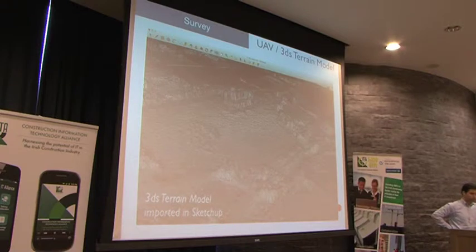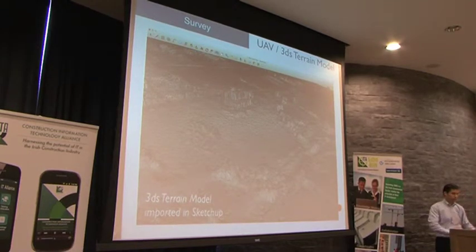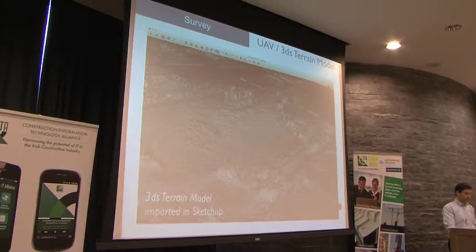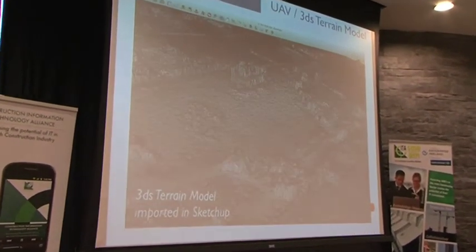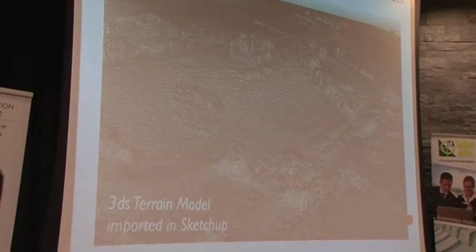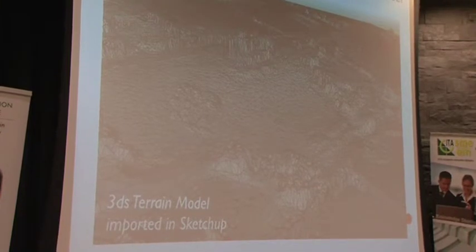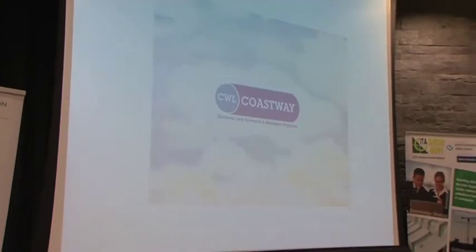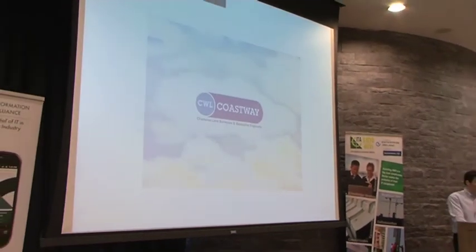So the surface mesh there, you can see the mesh basically takes the top of the trees and top of the building points, and a mesh will triangulate between all those points. But if you have just a pure geometry surface, I think input of XYZ coordinates or input of a mesh like that is just beautiful. But this is where the human intelligence comes into everything related to BIM, and you have to look at what is the information that's odd, the fact that surfaces don't triangulate over buildings. So this is computer technologies that are applying to this. Perfect, and that's one of the terrain models we have received.